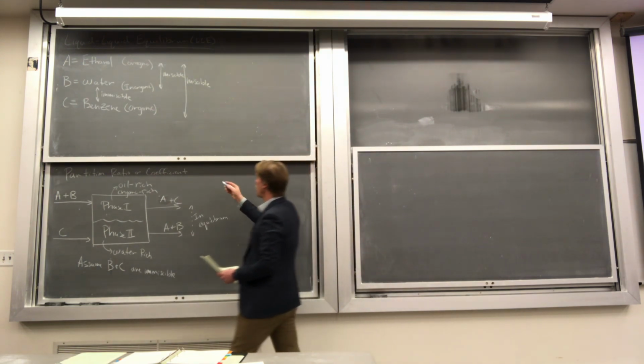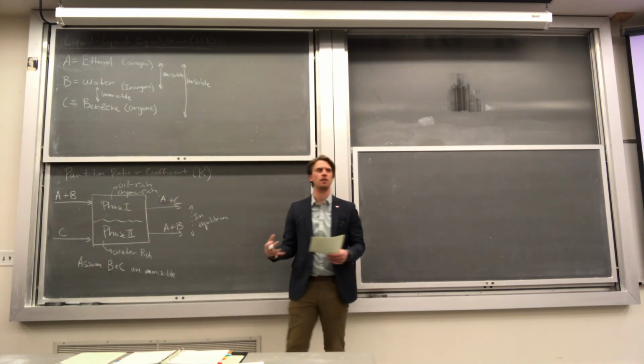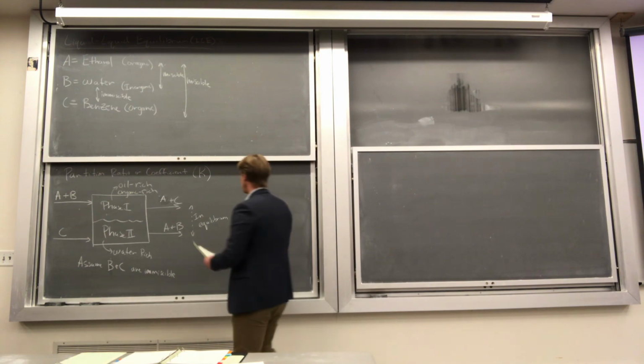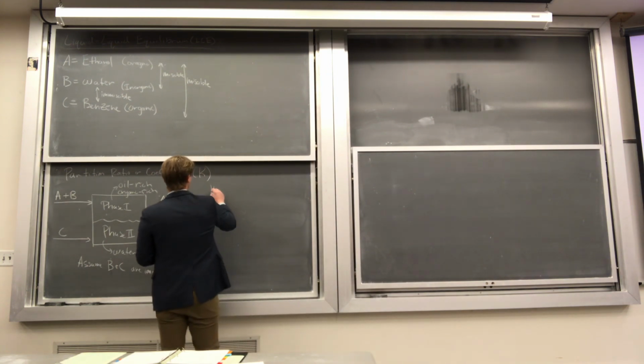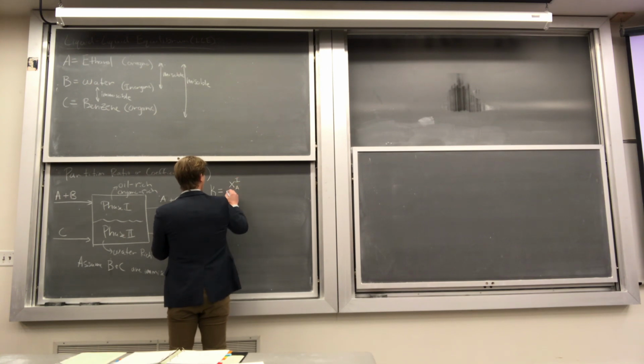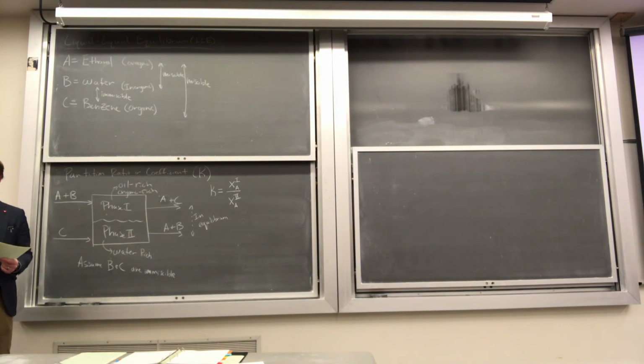So the partition coefficient, K, is going to be a design specification that we can use to solve these particular material balances. So K is going to be equal to the mass fraction, in this case, of A in phase 1 divided by the mass fraction of A in phase 2, right? Because we were concerned about getting the ethanol from one phase to the other phase.